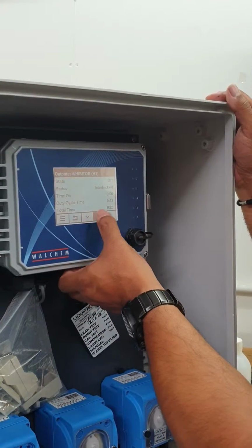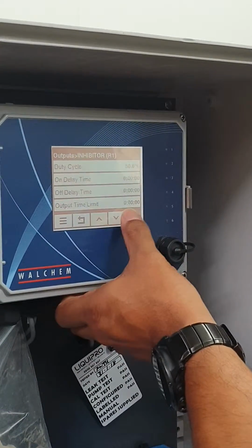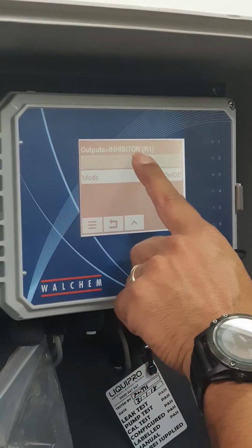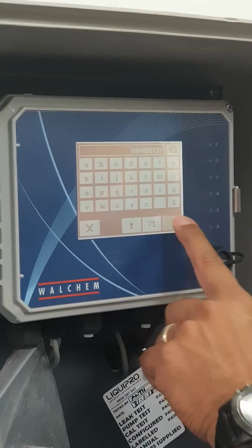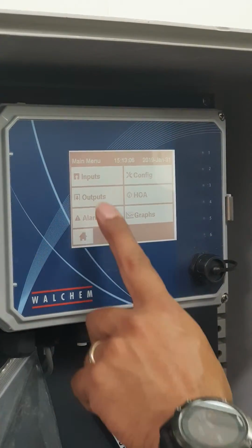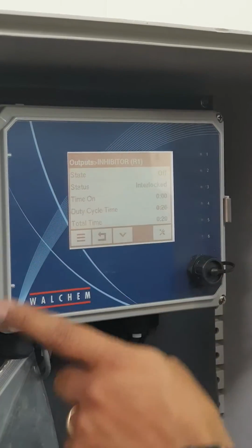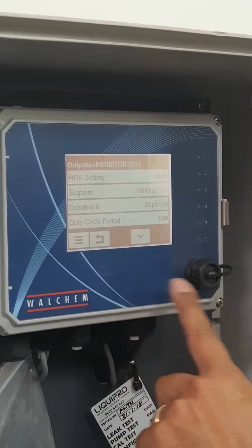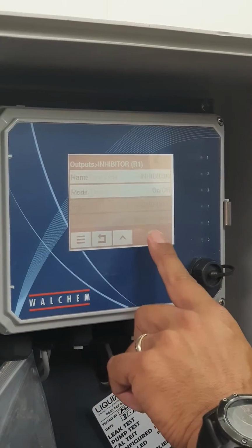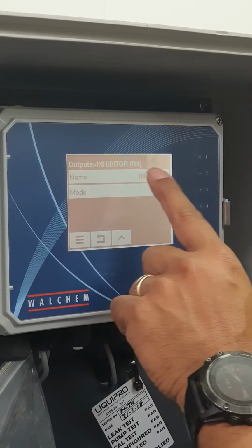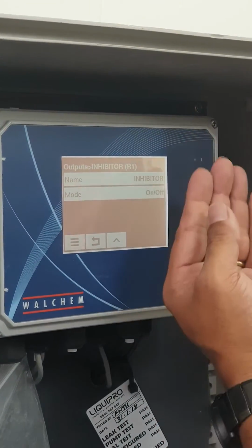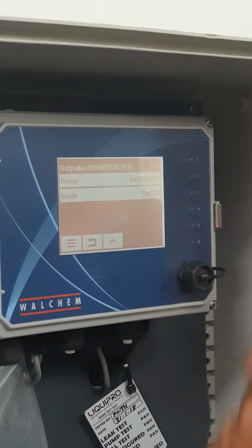And of course, the last thing I didn't show you, I'll go back in there, whoopsie, which is at the very, very end, is how to change the name, which is the same as the others. You go in there, you type away, and of course, tick the box, and then that name will be there. So just last thing to remember, in summary, outputs: select the relay that you want to change, press the spanner, but do go and set the mode first for what you're trying to do for that relay, because that will give you all the parameters in the menu when you select that output.